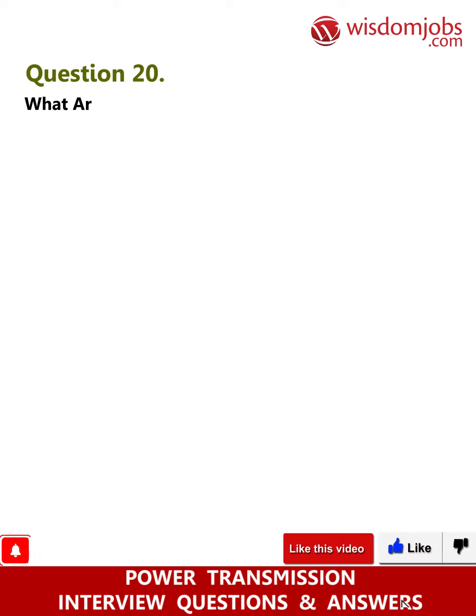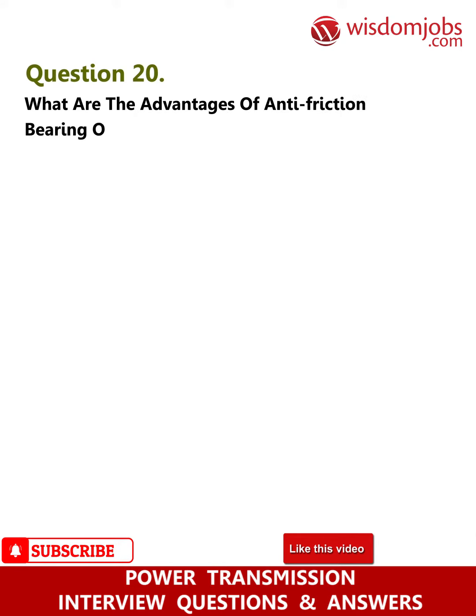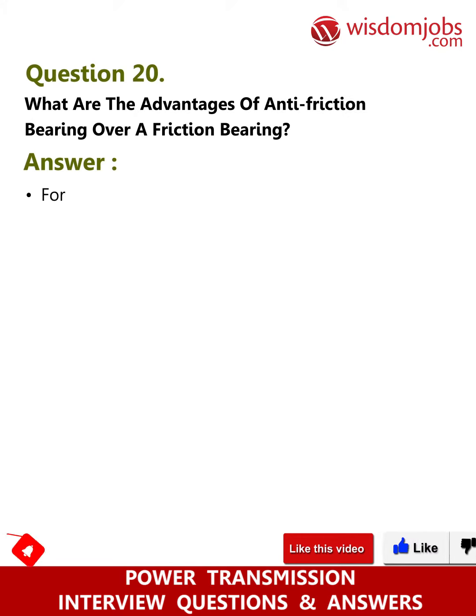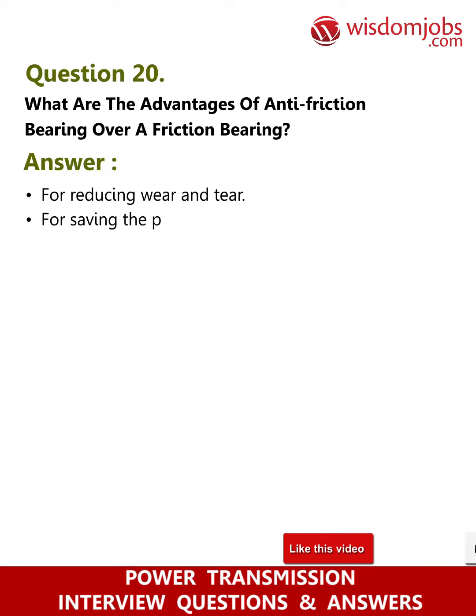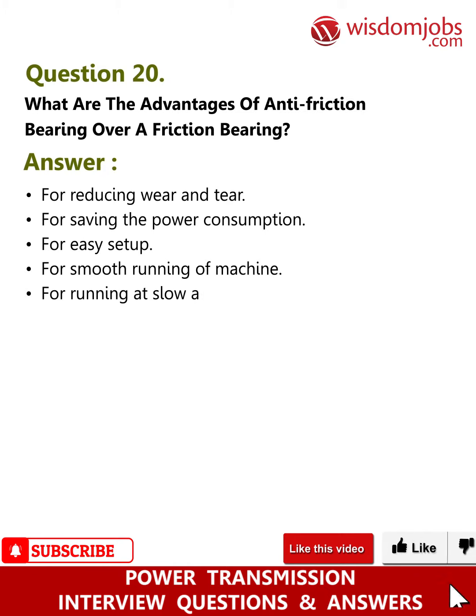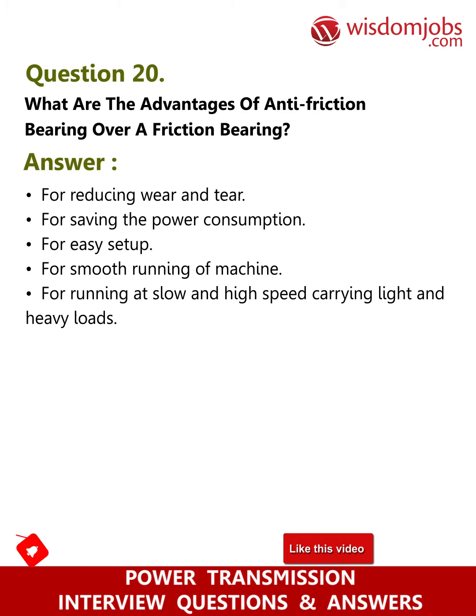Question 20. What are the advantages of anti-friction bearing over a friction bearing? Answer. For reducing wear and tear, for saving power consumption, for easy setup, for smooth running of machine, for running at slow and high speed carrying light and heavy loads.